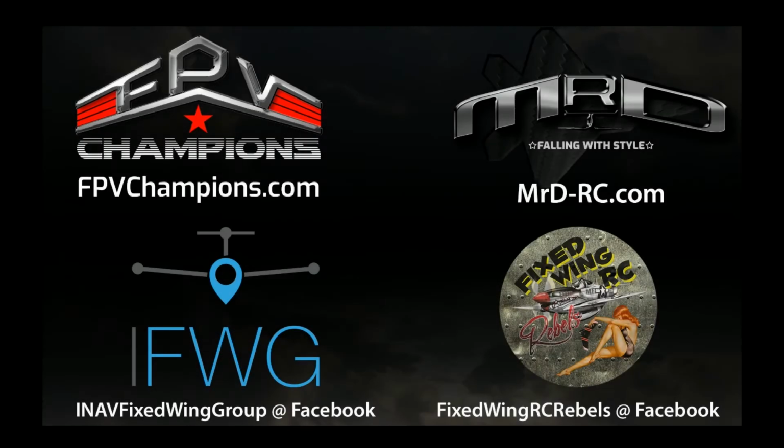Hey guys, I'm coming at you with a really quick Simplify OpenTX tip. In this episode, we're going to have a look at how to set up a mix so you can use both the aileron and rudder gimbals to control the rudder. This would be useful for something like a small 3-channel plane or a 2-channel glider. Let's get on with it.